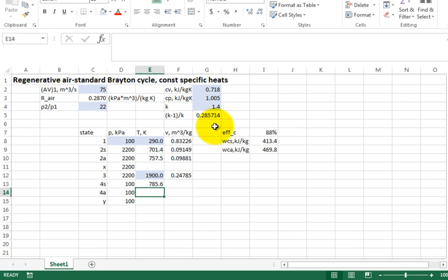Okay. All right, then I come up here and I say, okay, but I'm going to have the efficiency of the turbine, which for this problem, the efficiency of the turbine's 0.93. So it's 93%. Let's convert that to make it percent. Then we're going to calculate the work that the turbine would produce if it was isentropic expansion through the turbine in kilojoules per kilogram.